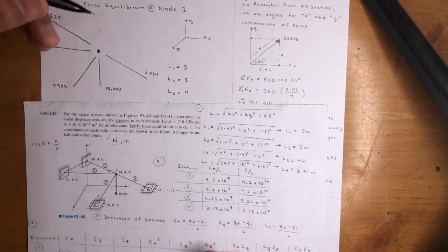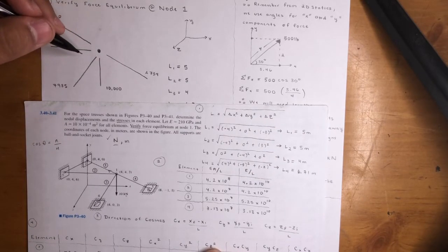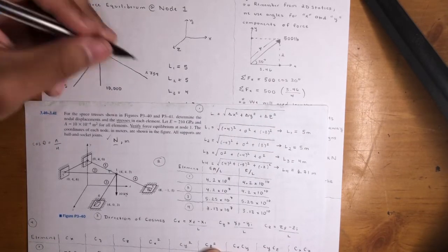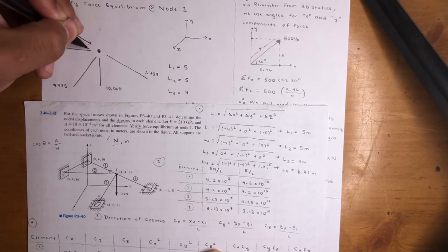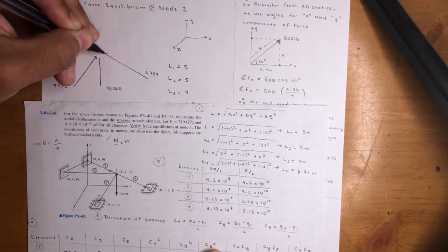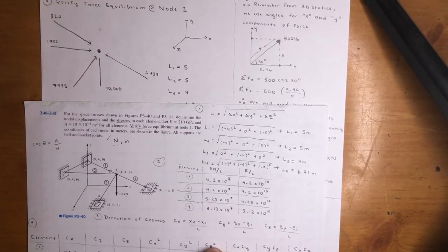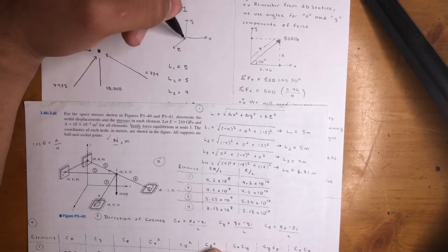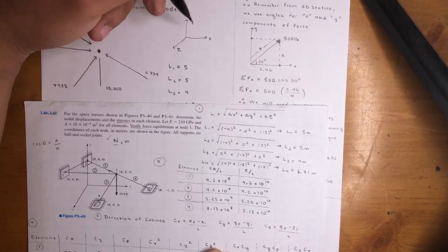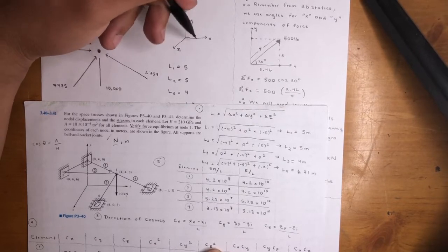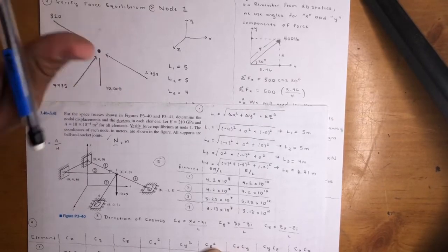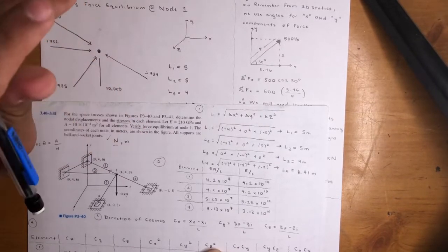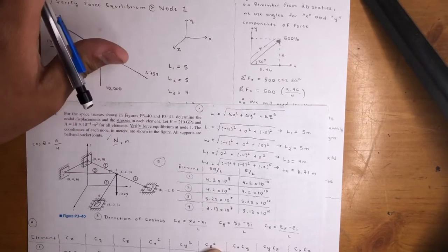Okay, now here's the thing. Compression points in, tension points out. So all of them were compression. Remember, they're all negative, so they're all going into the node. Okay? And this is our positive x, positive y, positive z, but you won't really need it. Don't confuse yourself. You might think, oh, there's a negative x direction, I'm gonna put negative 2734. No, just relax. This is only for 3D problems. It works, that's what matters.